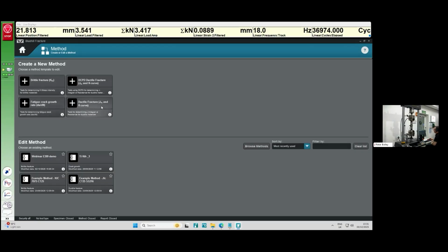Next to that, we have what's broadly labeled ductile fracture, where we're taking that from some of the language used in ASTM. More properly, we should call it elastic plastic fracture. There's some ductility, is the point. There's some plastic deformation and more gradual tearing that occurs as the material fails.